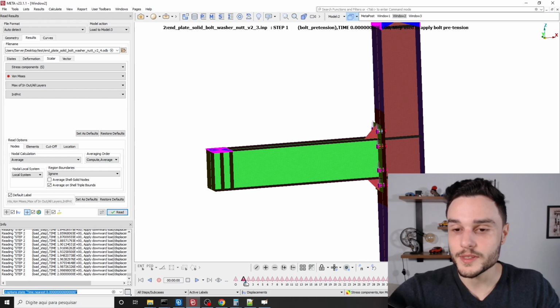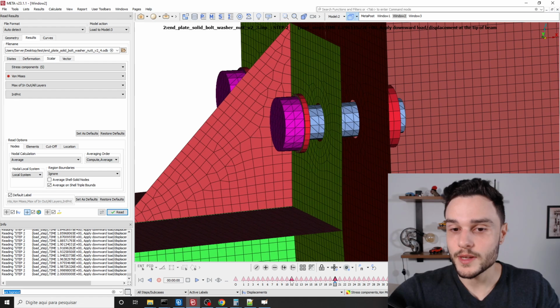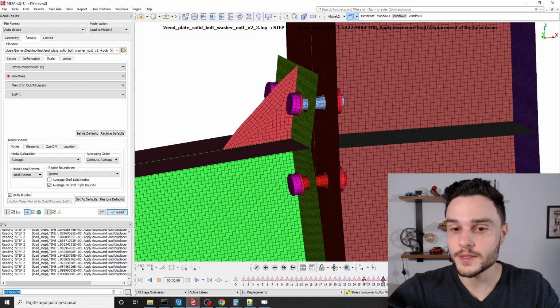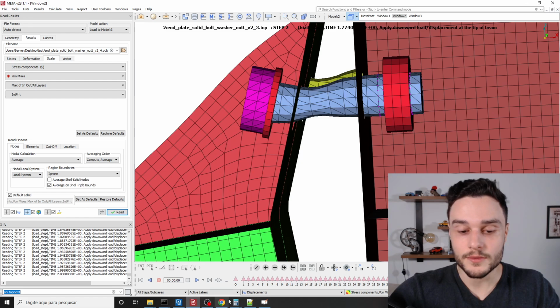This is what happens when we fix the material properties. We have this deformation occurring, and then we have plasticity occurring on this bolt. You see that we have a lot of deformation occurring here, because since we have the end of the curve of the bolt as a horizontal line, probably we have this whole section having plastic strain in that region.